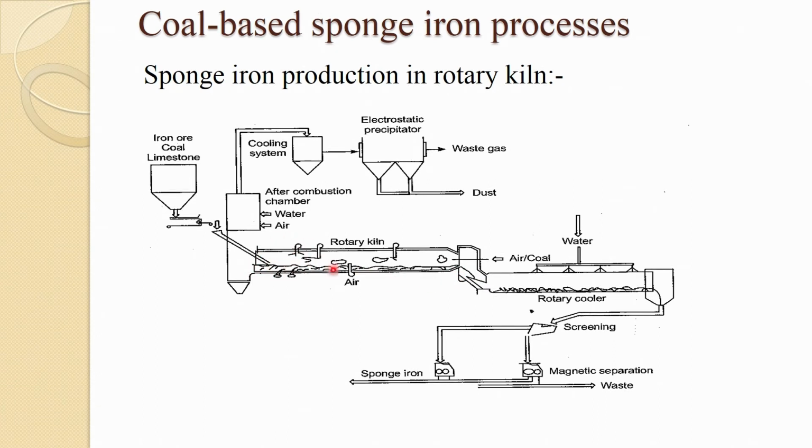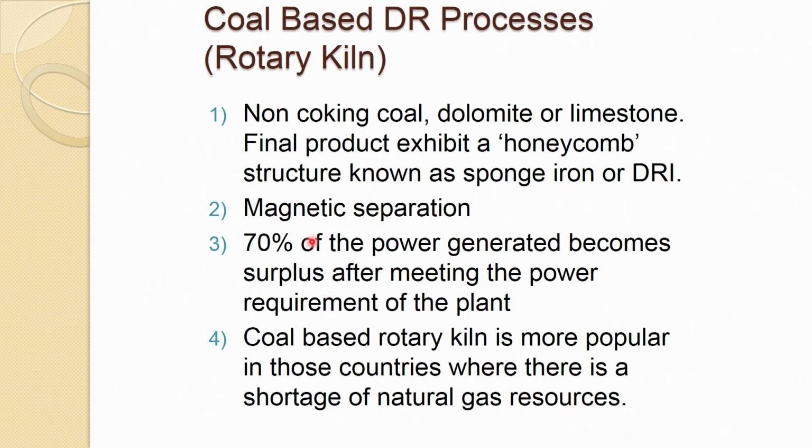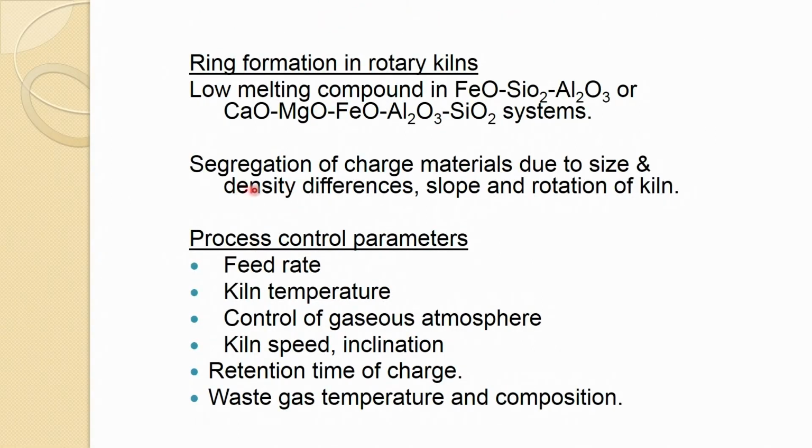When it is rotating, usually the centrifugal force and others also work, and the rotation of course is very small, due to which the segregation of particles of different size occurs, because there is not a close control on the particle size distribution. So, you have some range of particle size. That is why the segregation occurs. So, with smaller and bigger particles, your reaction also gets affected.